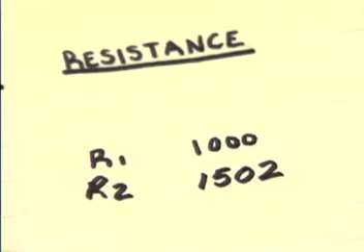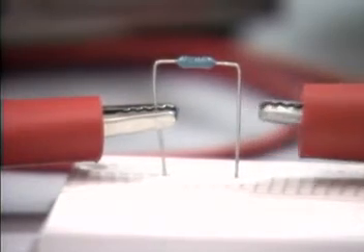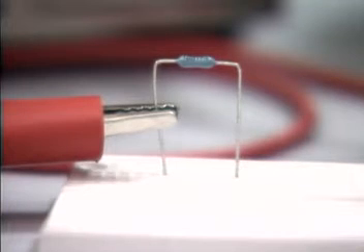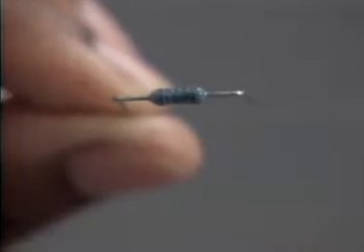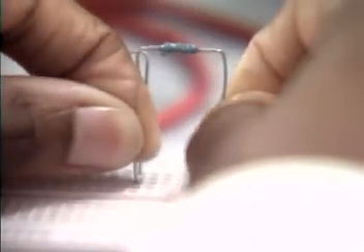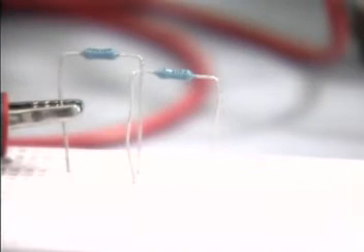under R1. Next, turn off the power supply and unhook the clip end from the right side of the resistor. Now, carefully insert the axial leads of this resistor into the breadboard. Remember, you're connecting this in series, so make sure to space the leads 5 or 6 holes apart and put the left lead of the second resistor in the same vertical line with the right lead of the first resistor.